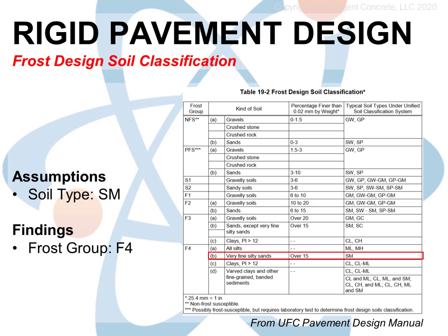Competent granite is much harder and stronger than concrete, and if water can reduce a mountain to gravel, it sure can tear up a concrete pavement as well as anything can. Freezing water in joints will damage pavements quickly through a process called spalling, but more to the point, freezing water in soil will cause it to expand and lift a pavement. When it melts, it can leave a void space behind, meaning there's a weak place under the concrete and a place where even more water can accumulate, causing even more damage the next time it freezes. A weak support location means that under heavy load, a pavement is much more likely to fail in that area.